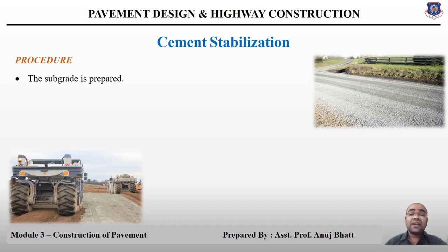Therefore care must be taken during screening with no prior preparation, as apart from stones and gravel, there is a risk of also removing lumps of clay and thereby modifying the properties of the soil. To prevent the lumps reforming after disintegration, the soil should be kept dry.